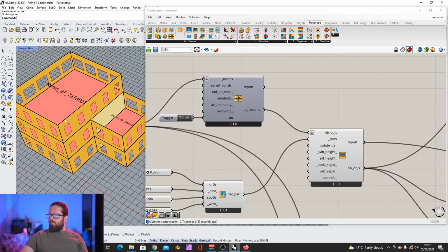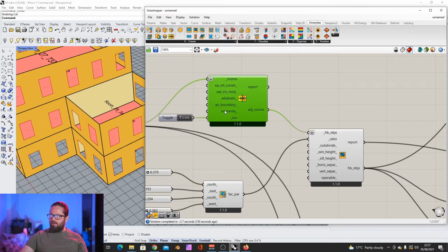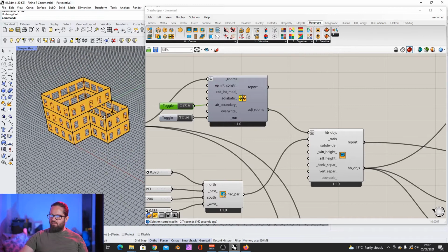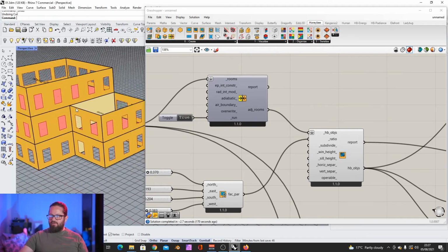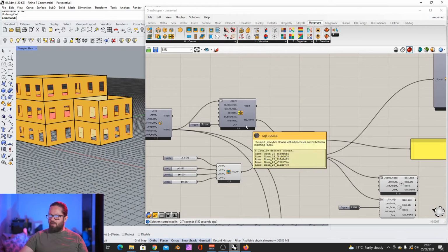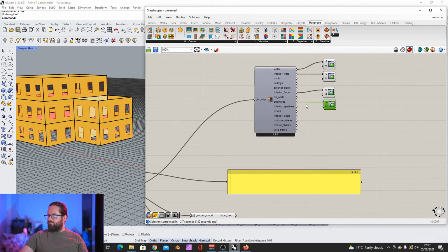That's if you want to delete these inner walls, then you can go here and go to air boundary, and that will basically delete all the walls inside. I don't want to use that, because it also deletes my floors. So for sure there are other ways to do it. Then maybe you need to do it separately. You can play around with this, of course.